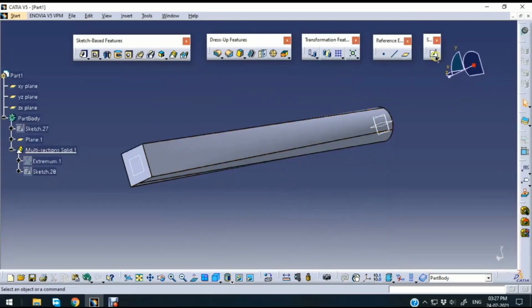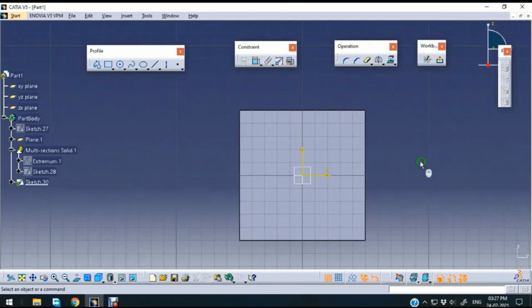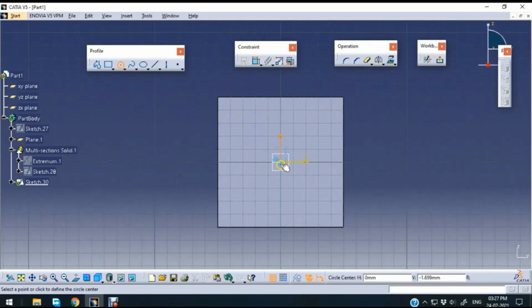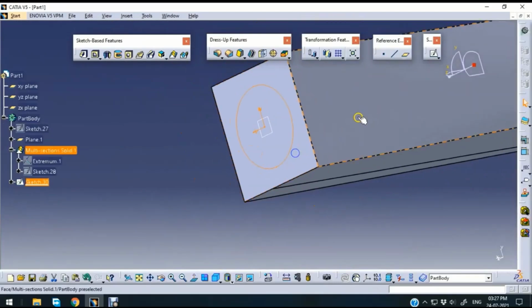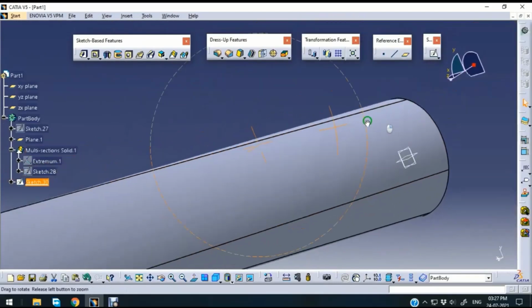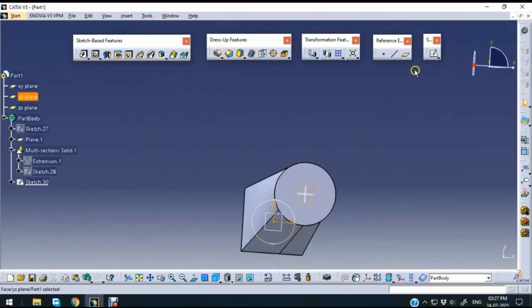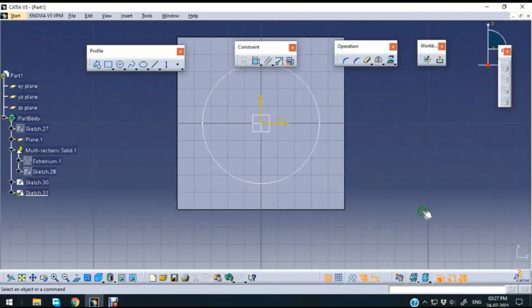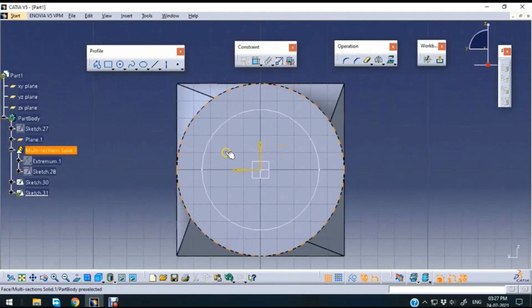so for example I will try differently. This side I need this circular profile. Okay, as in this side I need the circular profile. So I want to create the tube. So this side the cross section is a circle. This side I want to create a square. And use this normal view to change the direction of orientation, etc.